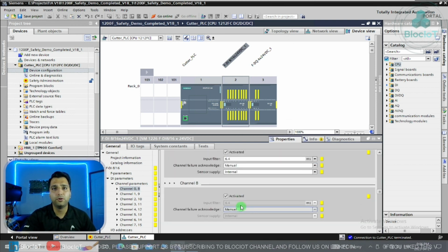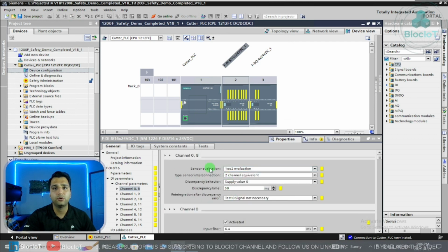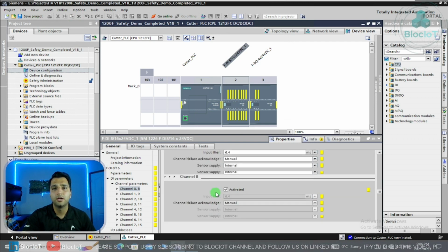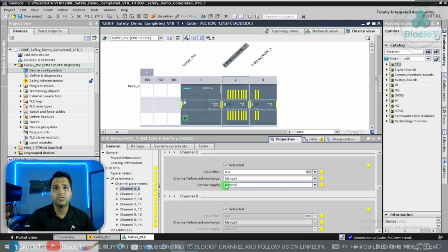And of course you can just activate or deactivate the channels, but I suggest to activate what you have basically wired up. If you haven't wired up an input, just disable them to avoid any accidental noises or just overall accidental behavior of your program due to the noise.